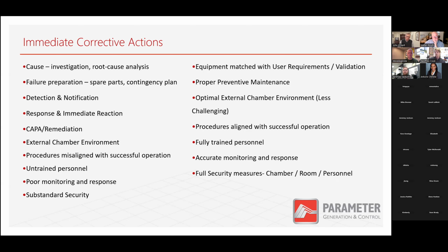The external chamber environment is a factor that is also easily overlooked. A lot of these chambers are operating at very precise temperatures and humidities, and those precise conditions are contingent on the chamber itself being in a well-conditioned area. So sometimes the ambient temperature outside of that area, and sometimes even the ambient humidity outside of an environmental control chamber, can affect the humidity inside the chamber, depending on how well the vapor barrier is sealed.